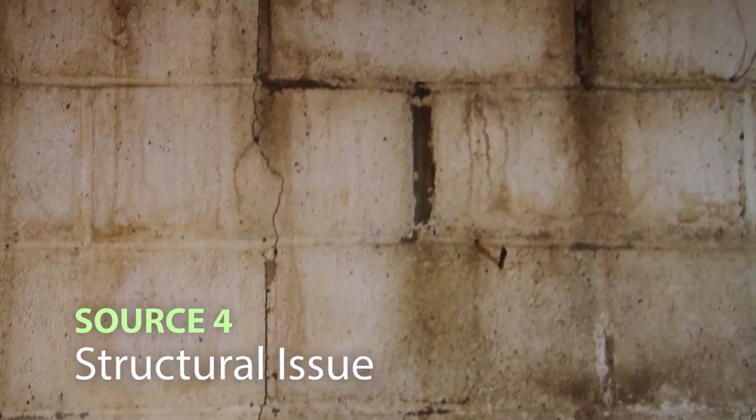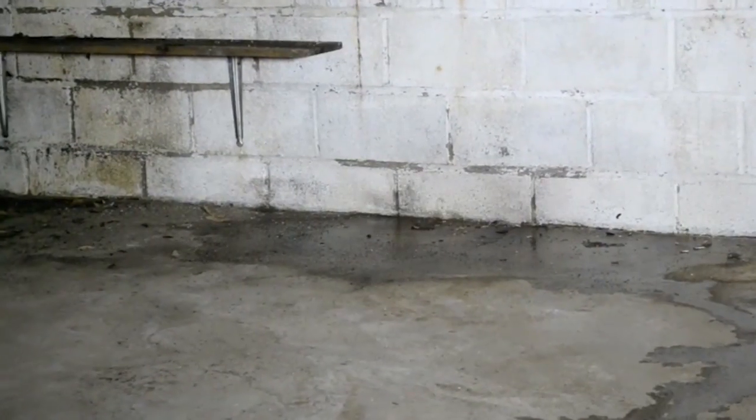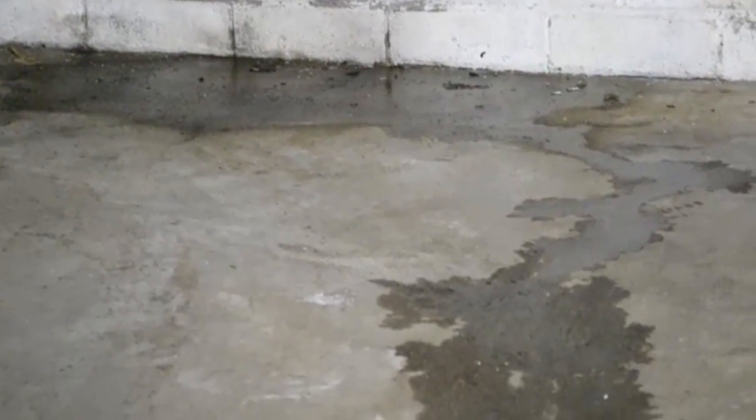Source 4 is a structural issue. This means physical damage to load-bearing portions of the home where the dwelling becomes structurally unsound and causes a water intrusion. Take a look at the foundation for cracks, holes, separation, or caved-in areas. Then determine if these are load-bearing walls.